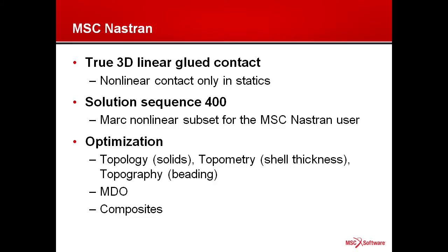Because of the Marc acquisition, Nastran has moved up to true 3D linear glued contact in all the linear solution sequences, and the statics has nonlinear. Again, this is something that helps on the NVH side, where meshes don't have to be synced and lined up anymore.